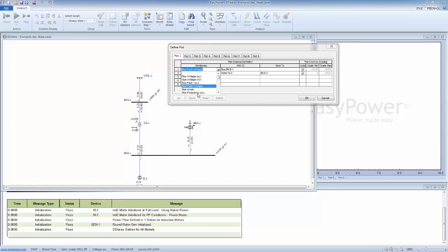If you have prepared a short piece of code, you know how difficult it becomes when you bring frequency into elements of a power system, because all the reactances and impedances, anything that has an F factor in it, including capacitors and inductors specifically, are going to change with the frequency.